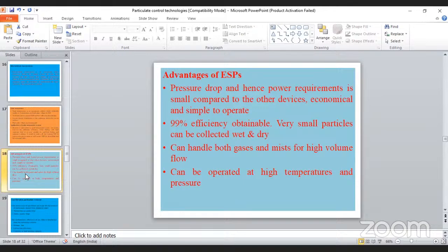With water or solids it's okay, but when we want to make a gas move in a swirling motion, it is quite difficult. We have to increase the speed in such a way that it makes the swirling motion, meaning the pressure must be very high. Only then does it make the flow in such a pattern, and only then will the particles settle down and slide down the walls of the cyclone. So that energy is needed here, unlike electrostatic precipitation and gravitational settling. In the gravitational settling chamber, you need not give extra energy, only certain energy at the inlet of the chamber.